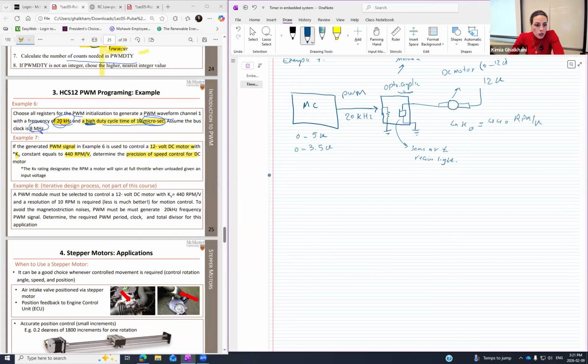First, these equations are important. Let's draw one equation. For RPM, what do I have? RPM equals kV times V average. This is going to be my first equation. I'm going to say this is my equation 1. Keep it in mind. Then I'm going to calculate this V average. I don't have it.